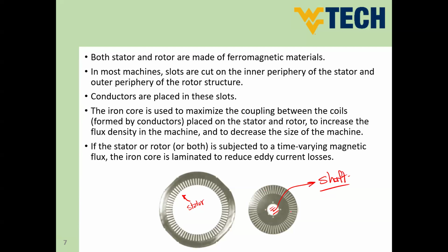So in order to have a rotating part, this is a section of the machine. When we collect hundreds of these sheets together, in the middle here, we will insert a shaft. This shaft bar will be supported by what's called bearings in order to allow our machine to rotate with minimum friction. Okay, and we will see more detail about the structure of a complete motor in a few slides.